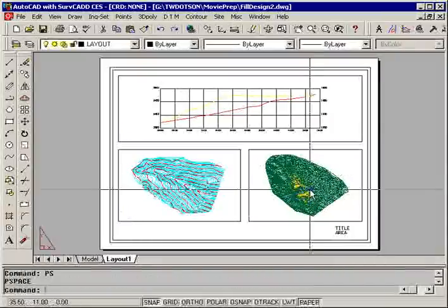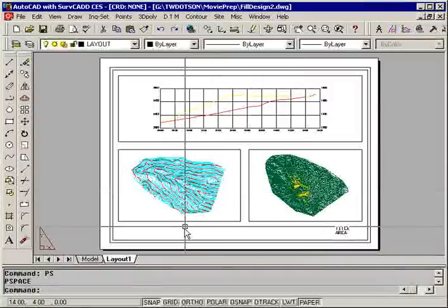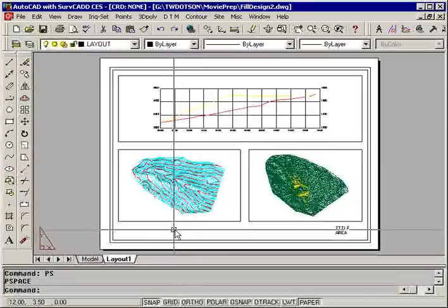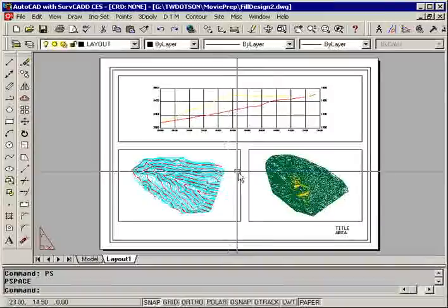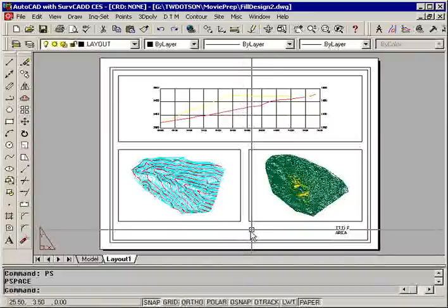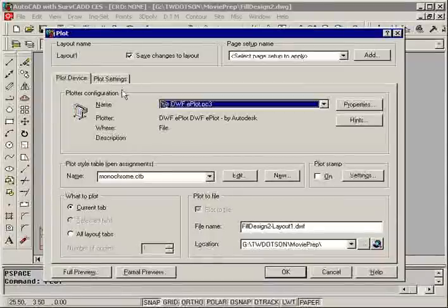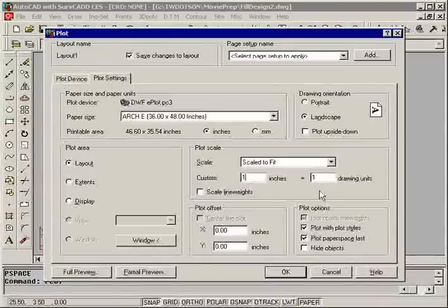Important factors, of course, you could switch back to paper space, issue the dtext command, and annotate the scale of each viewport. You could do additional details in this, and having none of it affecting the model space area. Very critical point when you plot, issuing the plot command. The most important factor when plotting from paper space, regardless, is that the scale is specified to a 1=1. Do not put any inch marks or foot marks. 1=1 when you plot. Cancel.